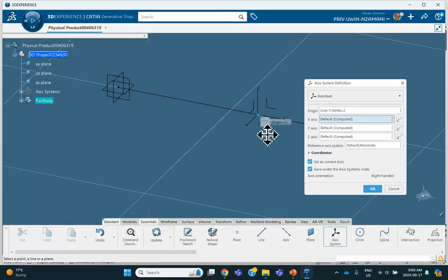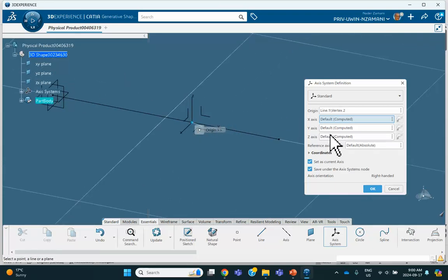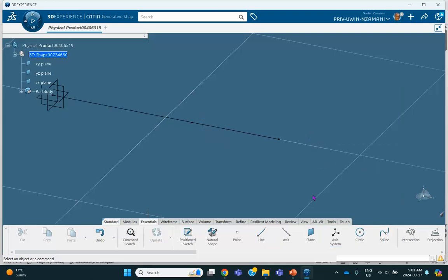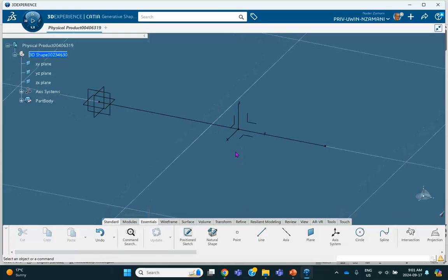That's where the hinge is going to be. And notice that X is pointing this way. You can change the direction of X by selecting a different orientation. For example, if I select the X-axis, I can put it on this line. I don't want to do that. So, no selection. Let me cancel that and try it again. There. X is in this direction. Very good. If I didn't do this right now, I would have to come back and do it later.